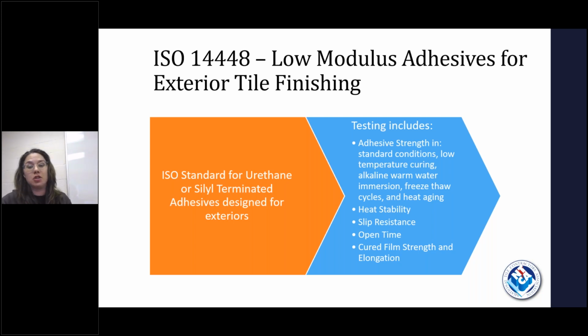This testing includes a lot of pretty intense stuff. We're going to test the adhesive strength in standard conditions, low temperature curing, alkaline warm water immersion, freeze-thaw cycles, heat aging. We're also going to check the heat stability and, similar to the ANSI standards, slip resistance, open time. And then they also do some testing because this is more of a film. So instead of like a mortar where it cures and it's somewhat brittle, this is almost more like a crack isolation product. It's not, but it kind of has more of the feel of that once it's cured, that it does have a little bit of play to it or flex.